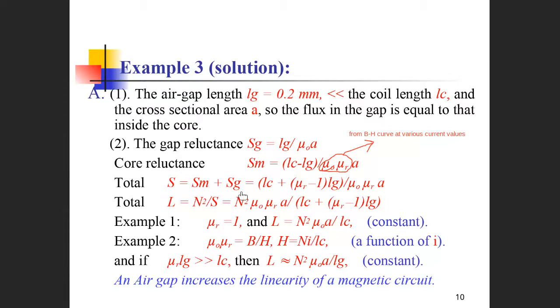For your good understanding, we write it in this way, not breaking it into figures, because we would like to give you some of the general characteristics of the examples. Given the coil's total reluctance and turn number, the inductance is, once again, the turn number squared over the reluctance.